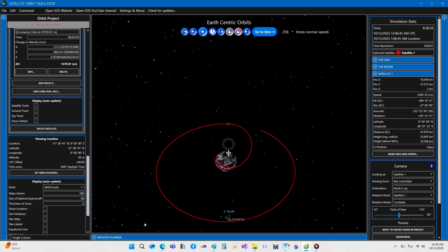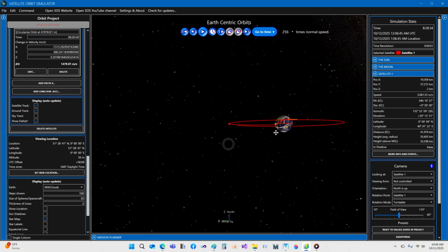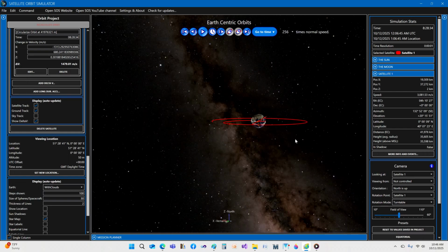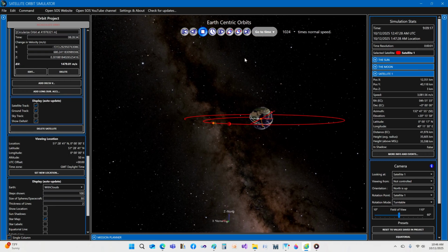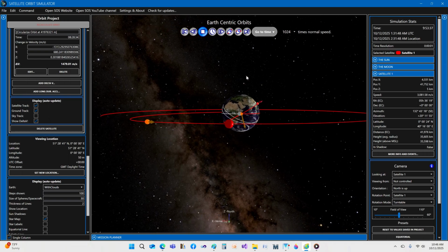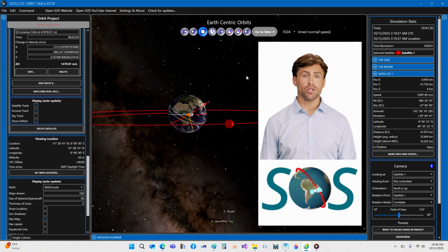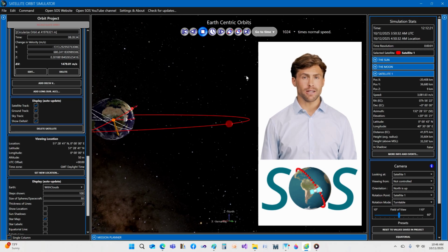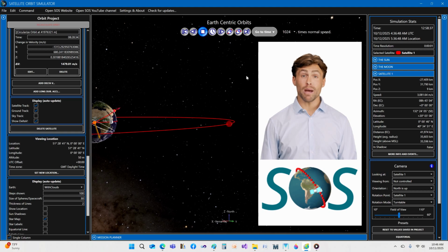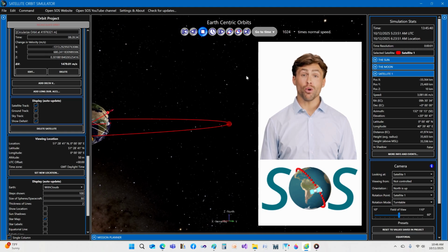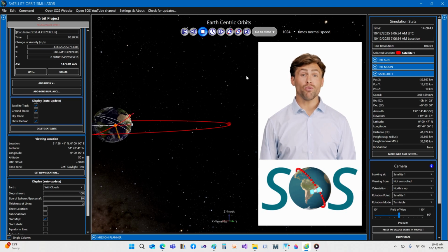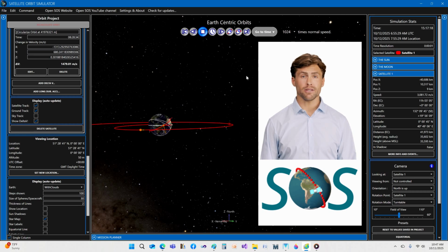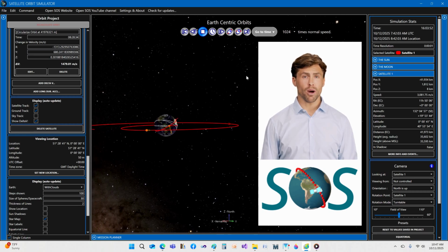The spacecraft is now in geosynchronous orbit, but only a portion of that orbit can be seen. Change the simulation speed to a larger value and run the simulation. Verify that the satellite settles over a particular longitude. To choose your own final longitude, you must change the timing for the Hohmann transfer burn accordingly. Note that each rocket burn, measured as a change in velocity, is recorded for you. You can use this value in the rocket equation, along with satellite mass, to calculate the rocket fuel mass required.